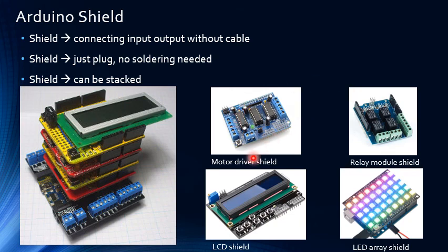But as you can see, the choice of shields is not large. So this is good for learning, for the basic learner, because it can connect input and output without cables, just plug, no soldering. And if you have more than one shield, they can be stacked. You can put this one on top of this one, it's fine, it's still connected.